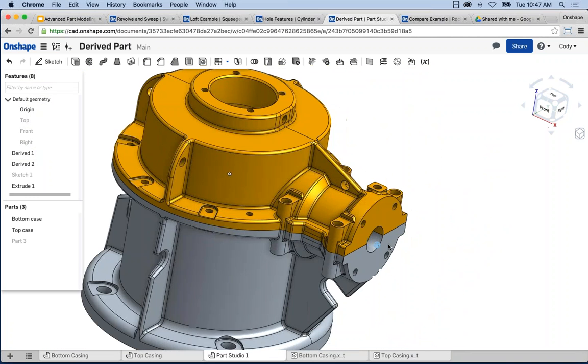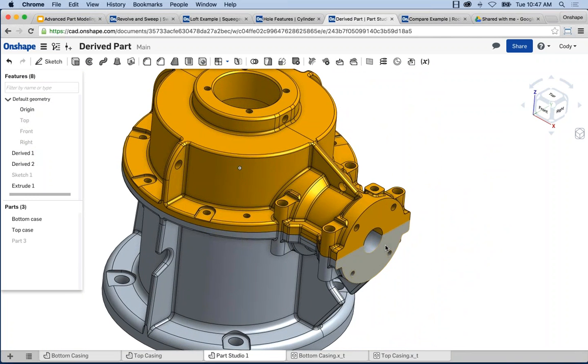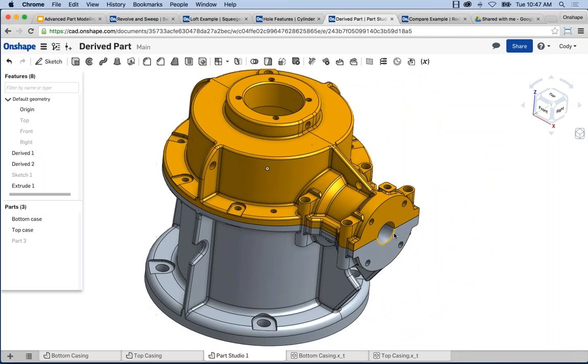I like to use the example of imported models, but again, it could be your own models, your own sketches. It really depends. But it is a technique that oftentimes is very common, kind of this master model technique, where one tab, one sketch, one feature, one part may drive everything. And then, you have a whole bunch of things that may be linked to it. So that is the derived feature. You can use it, again, insert parts, sketches, whatever it may be.